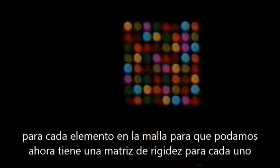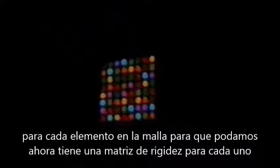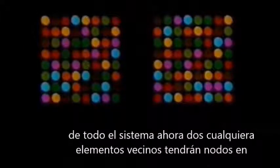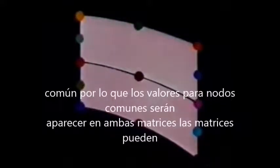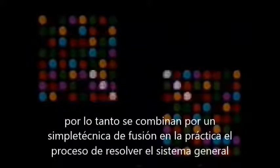We carry out this process for every element in the mesh, so that we now have a stiffness matrix for each one. The important step now is to combine all these individual matrices into a single large matrix representing the stiffness of the whole system. Now, any two neighboring elements will have nodes in common, so values for common nodes will appear in both matrices. The matrices can therefore be combined by a simple merging technique.